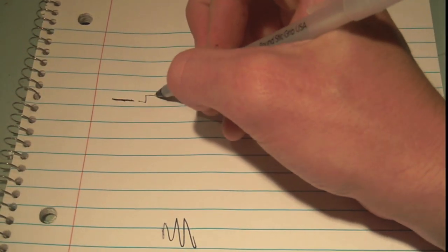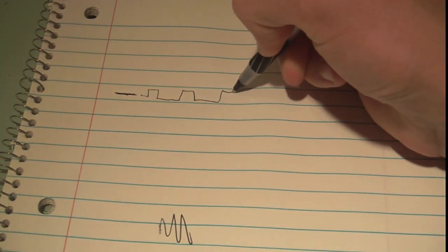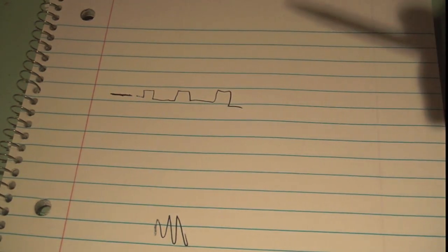This is sort of the broad system diagram of how this might work. You have your microcontroller's signal output here. You can see why I chose it, because it only takes one signal out, and you can bit bang a PWM, so you don't even need hardware PWM. Then you have your PWM signal here, maybe something like a 20% duty cycle. I'm going to be assuming you're familiar with PWM for this.